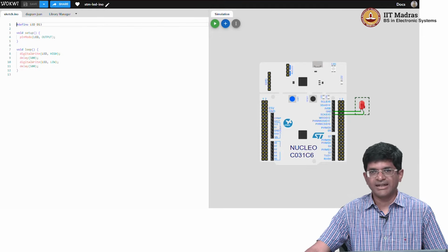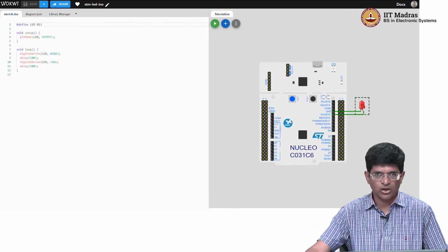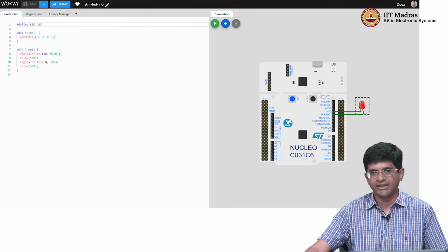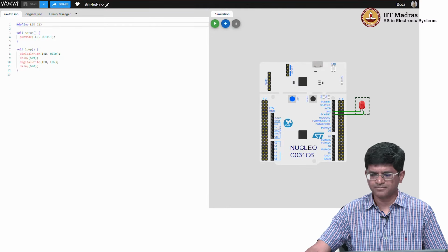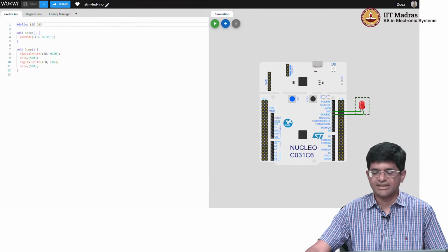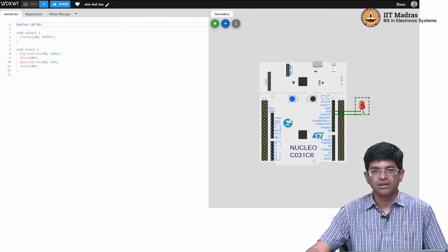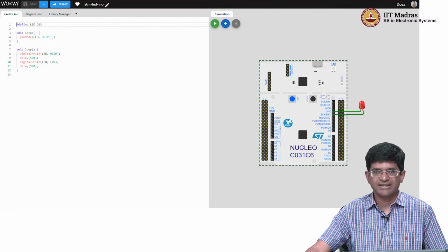Now if I just turn an LED on and that's all that happens, that's fine, it's already a good sign of life that something in the system is working. But it could also be just that it happens by accident, that somehow I managed to connect a high voltage to the A terminal and the C terminal is connected to ground, and therefore the LED glows. How do I make sure that this is actually happening?